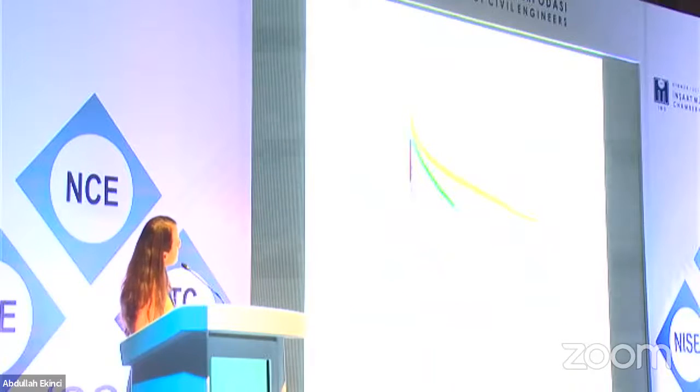When performing several tests in one sand for different initial relative densities, as you can see here in the presented graph, it is obvious that the rate of the pore water pressure buildup depends on the initial relative density, and as is also obvious, it's decreasing as the initial relative density is increasing. Now, for each one of these tests, we can determine the CL value. When plotting the CL value against the initial relative density for these different tested specimens, we see that obviously there is an exponential decay between the CL value and the initial relative density.